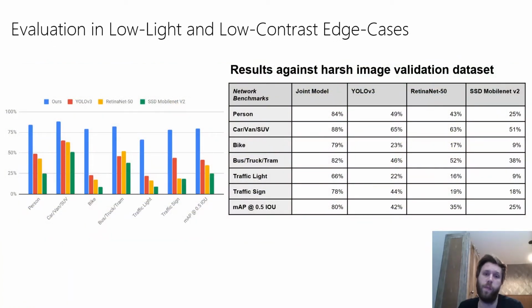And so we have also done some quantitative evaluations in low light and harsh weather scenarios. And to do that, we've acquired a harsh weather data set over about 2 weeks of test drives in North America. Size is about 10,000 frames. And we have compared the traditional sequential approach, that is a traditional ISP with handcrafted expert-tuned parameters, plus a fine-tuned detector on top of it, with the joint proposed approach. And what we measured is about 30% improvement in mean average precision for these harsh cases.